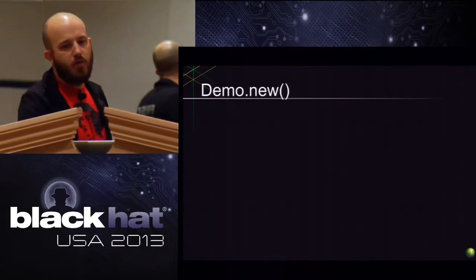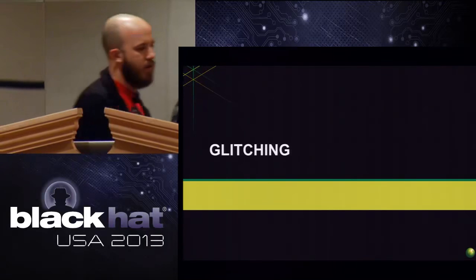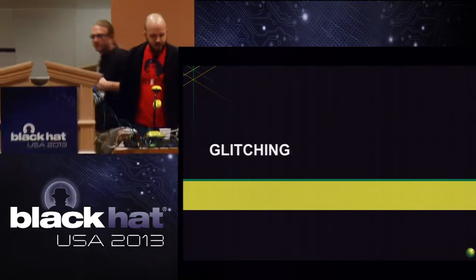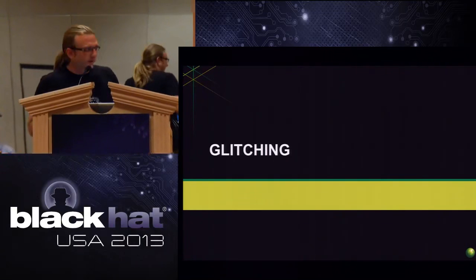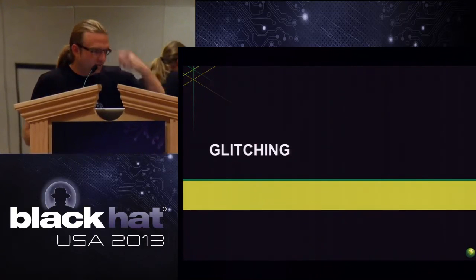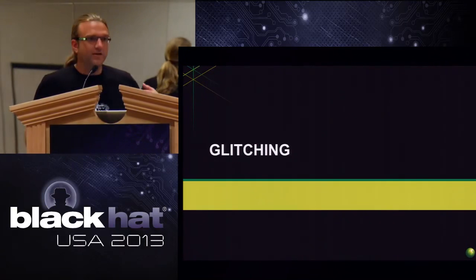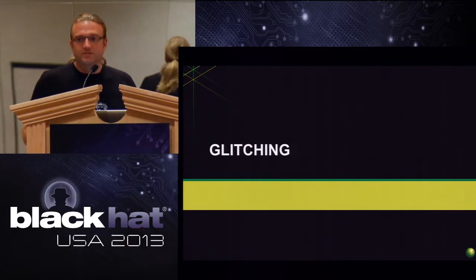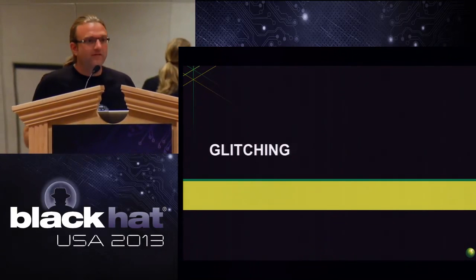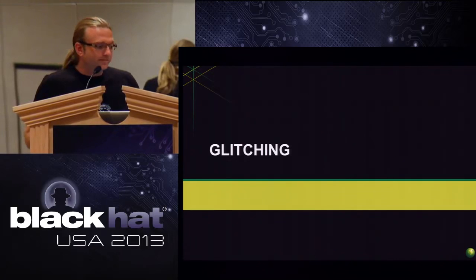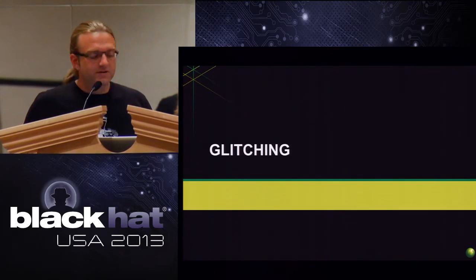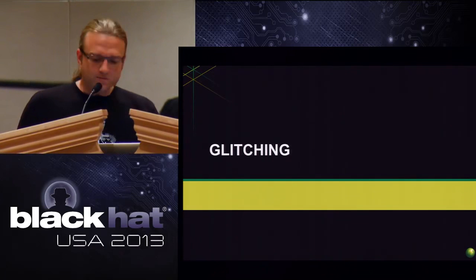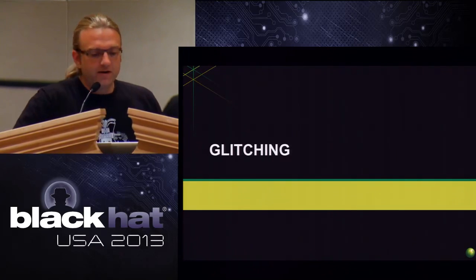I think we've got a couple minutes that we'll cover glitching real quick. If you remember way back, we talked about there's some bits that can be set that don't let ICE be enabled anymore, so you can't actually do any live debugging on the board, unless you magically hit it within that first 30 to 60 cycles. Once you do, you can get away from that.